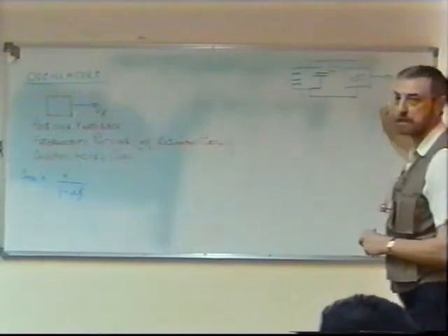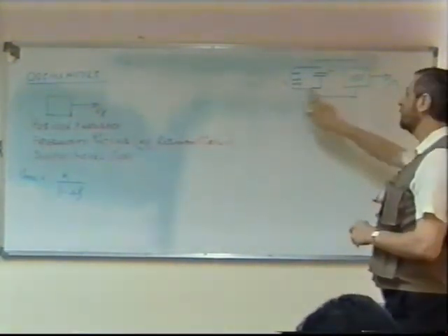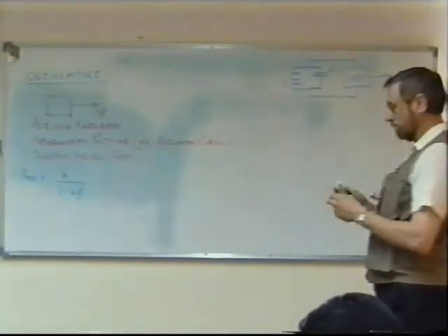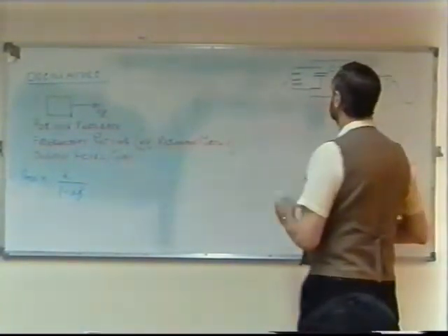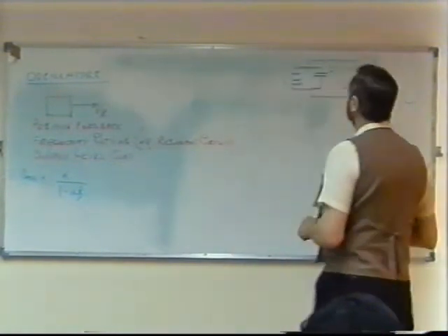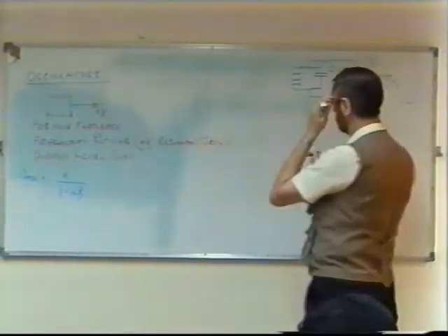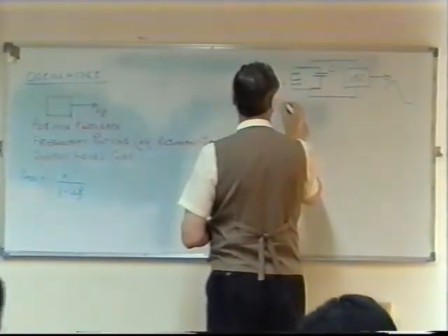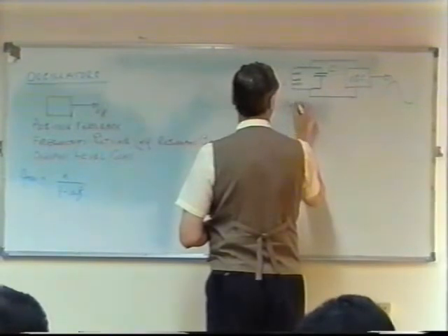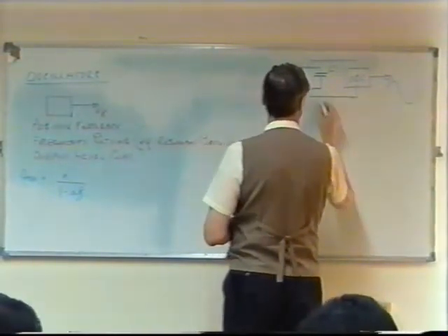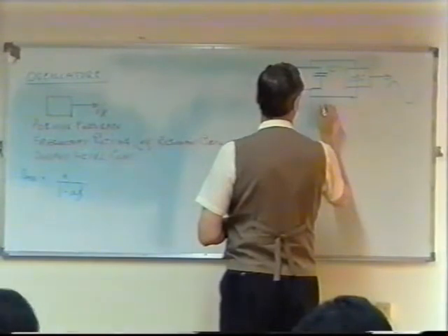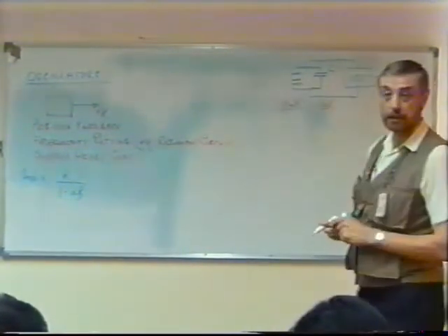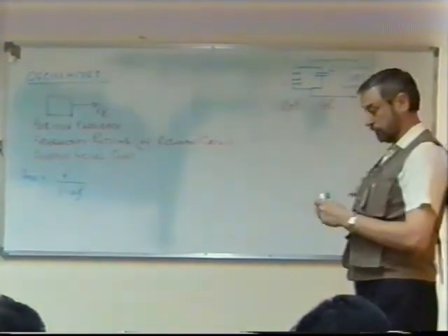The frequency of that sine wave depends on the resonant frequency of these two components. Now, if I give you the values of these components, you should be able to calculate for me what the output of this oscillator would be. For example, let's say I have an inductance of, say, 10 millihenries, and a capacitance of, say, 5 nanofarads. Quite small values. Can you work out for me?